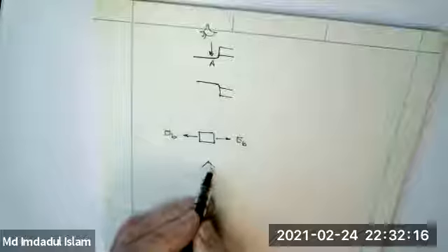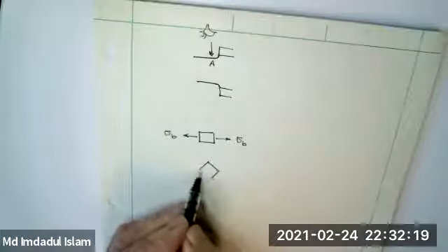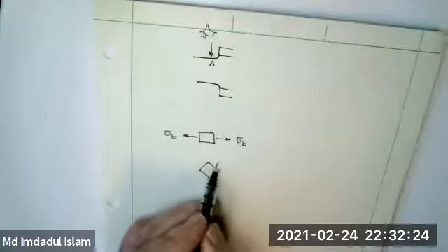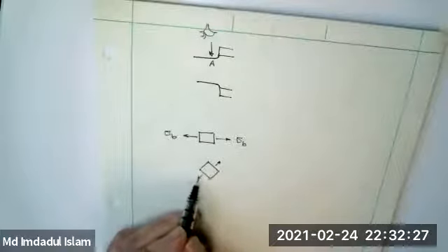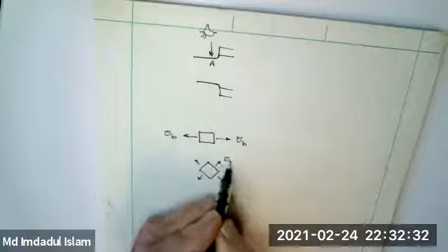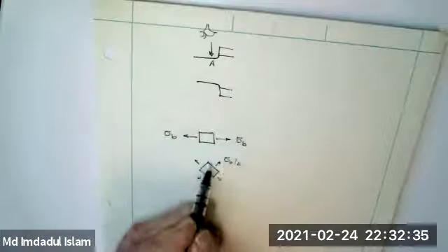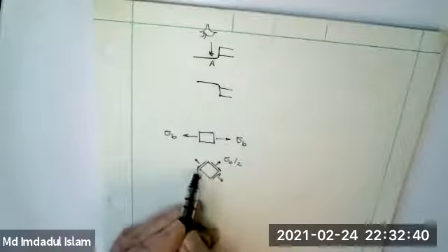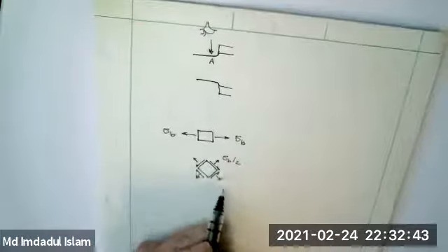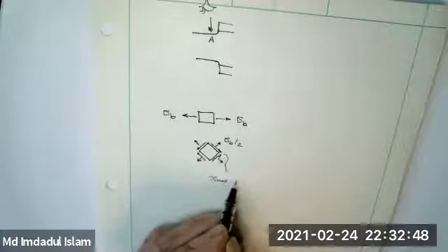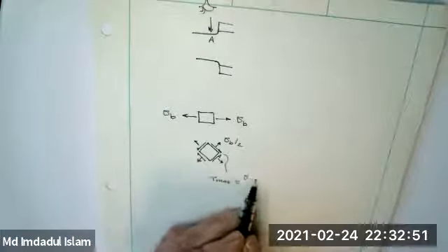So if you look at a 45-degree element, this is tilted by 45 degrees, then the stress state has become biaxial in terms of normal stresses. But some of this stress has been converted into shear. And this is tau max equals sigma B upon 2.